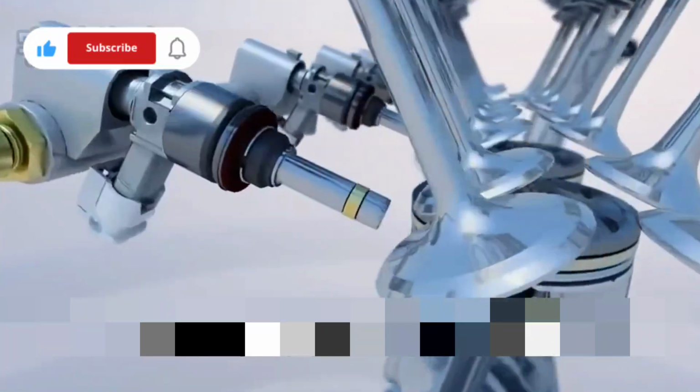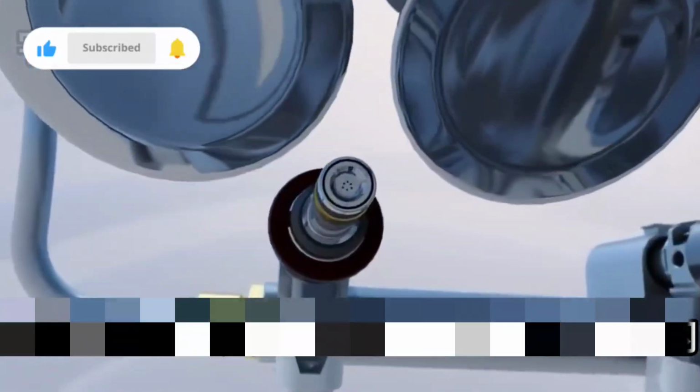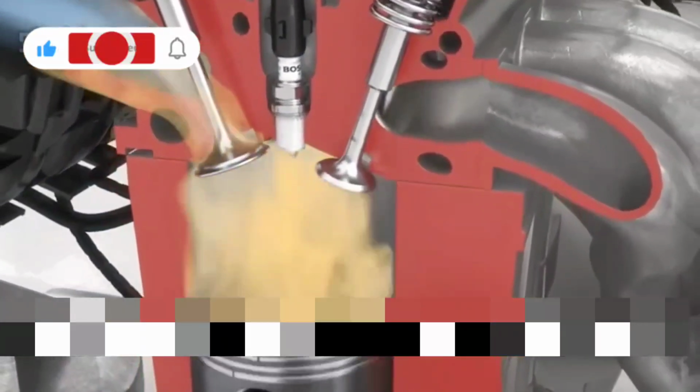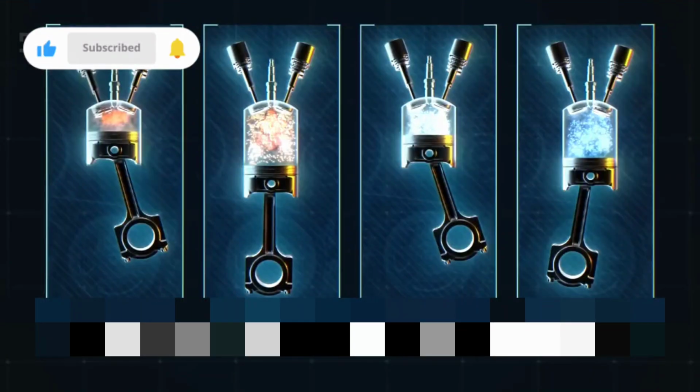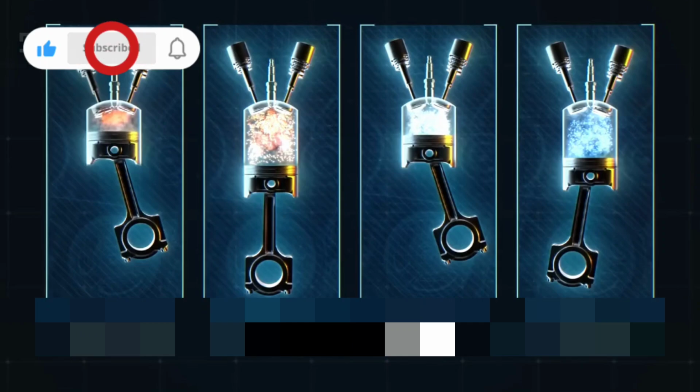The fuel pipe reaches the fuel injection nozzle in the engine. The fuel injection nozzle is a pressure relief valve that can spray fuel into the engine in an atomized manner. When the atomized fuel enters the engine cylinder, there will also be air entering, and they will be mixed according to the air-fuel ratio of 14.7:1.